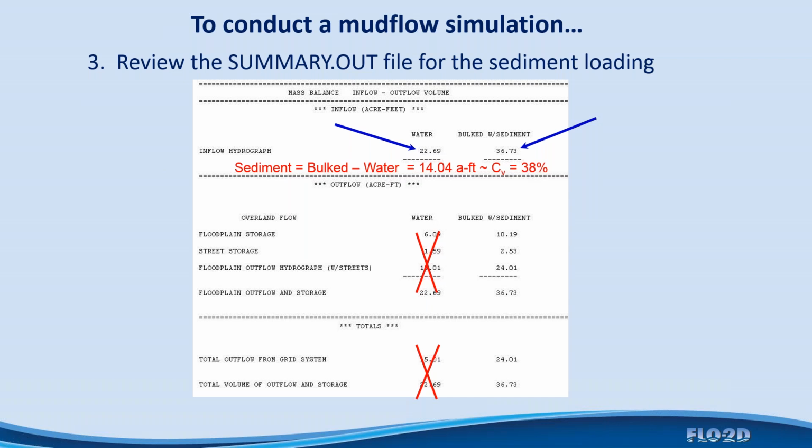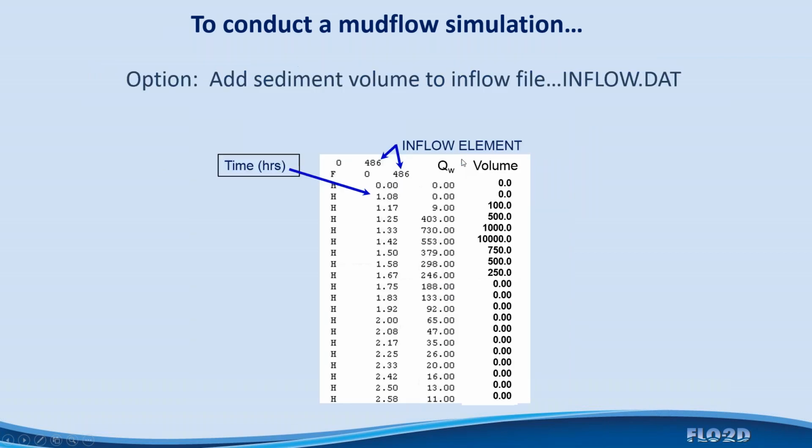And that's what you need in order to have a mud flow event. If it's less than around 25 to 35% concentration by volume, you can't have a mud flow event at all. It's going to be totally fluid throughout the entire event because the peak will just catch up with the frontal wave and dilute it. And the frontal wave might slow down until a point where it gets near the fan apex, but after that, it's all mud flood. So if you don't have this in a relative range of 30% concentration by volume or higher, you're not going to have a mud flow event.